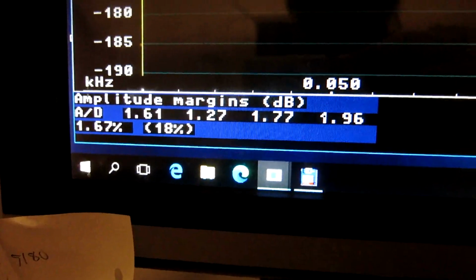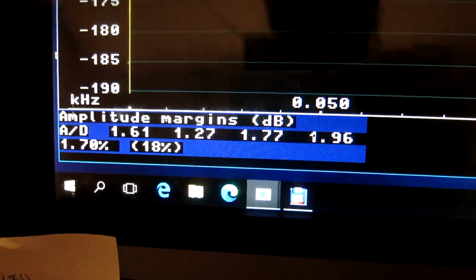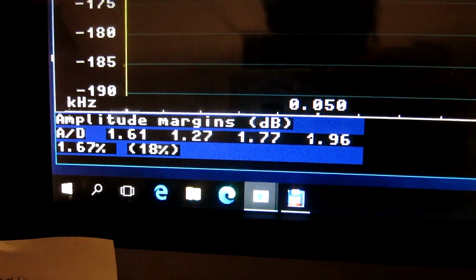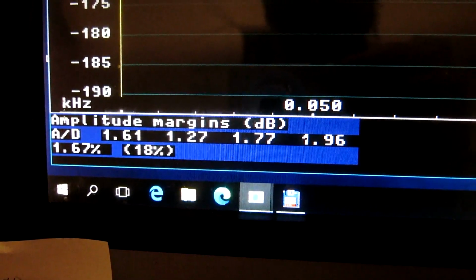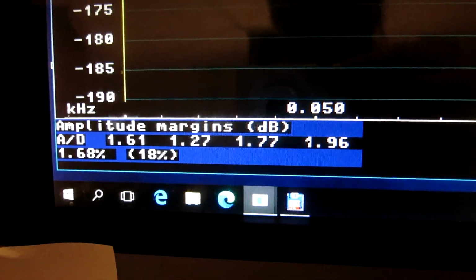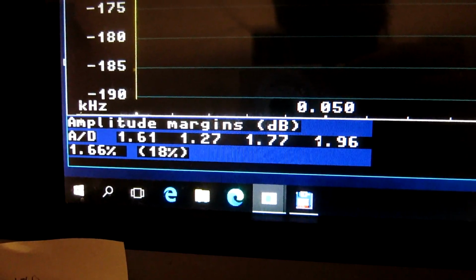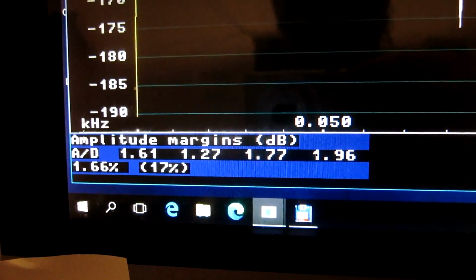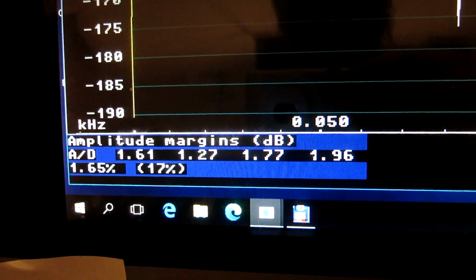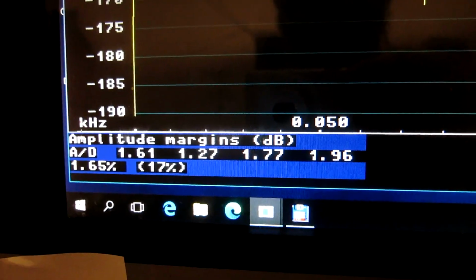I have removed the 10 dB attenuator and now the signal level into the unit is plus 13 dBm. But the level has only increased by 5 dB, which means that the diodes are limiting by about 5 dB now.